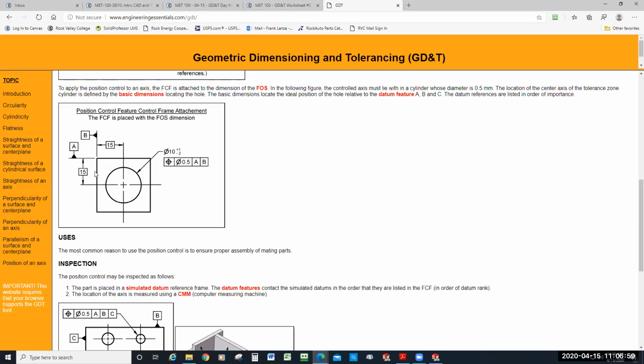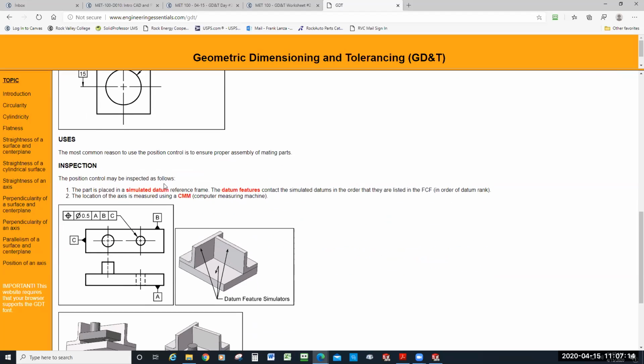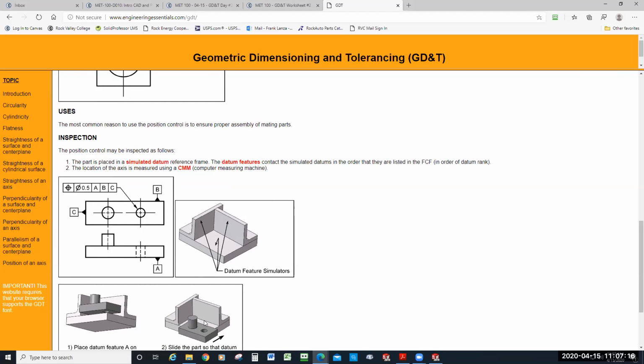Like I said, if somebody's just saying, well, hey, I'm going to put a pin in here and measure from here to the end of that side of that pin and subtract half the diameter, and it comes in both ways just fine, well, that's great. But if the pin doesn't go all the way down, or they've got a plug that has a shoulder on it, so that it only goes in a certain depth, they don't know for sure what the other end of that hole looks like.